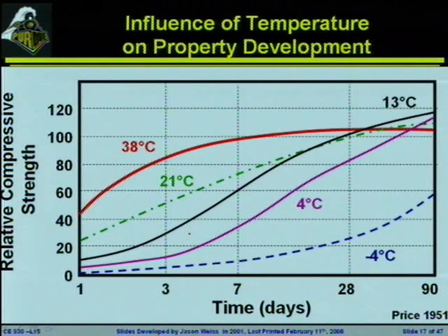Other questions? Okay, if we start to look at the relative development of strength, this is some data from the 1950s, but there's no reason why we would think this would be anything that wouldn't be similar to what we would see today. Zero strength, obviously, down here. 100% of the overall compressive strength at 28 days would be shown here.